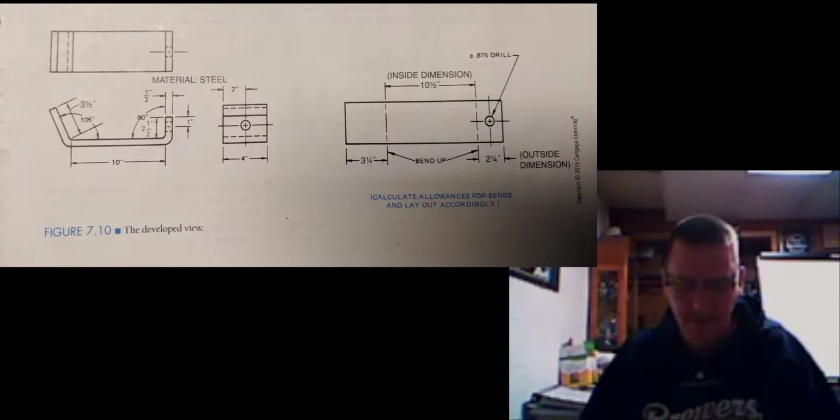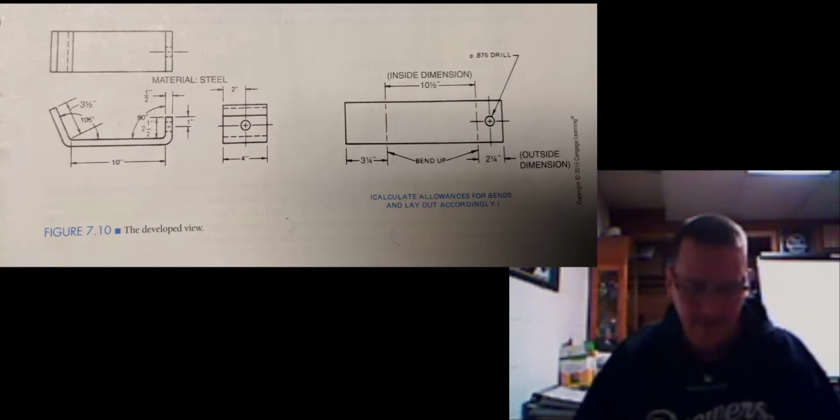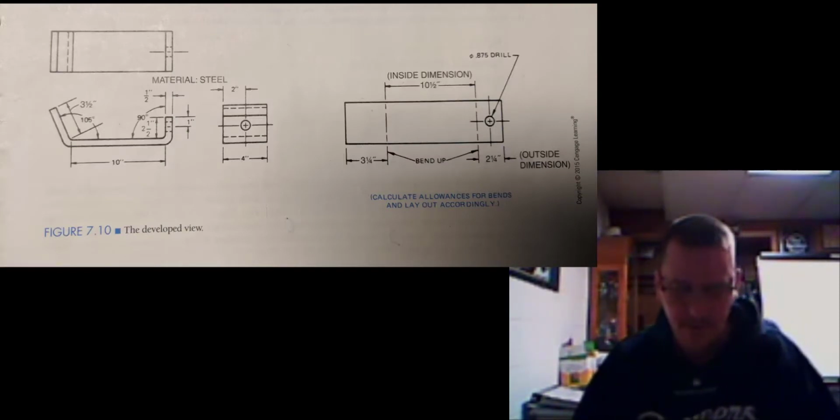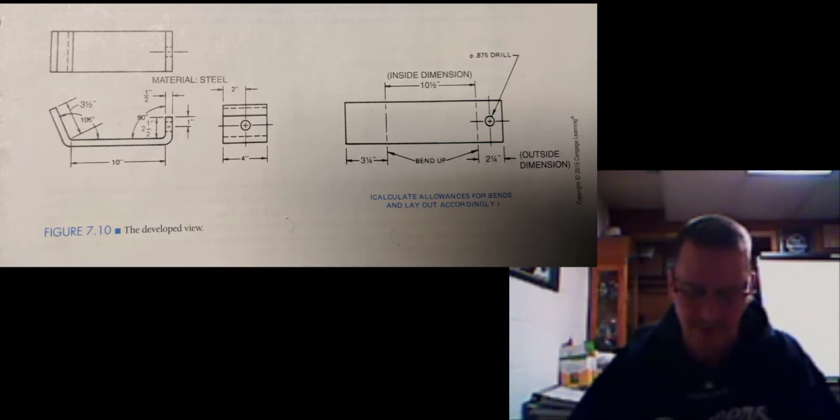Now we come to one of my favorite viewpoints. These are called developed views. A developed view is also called a development. It is a view of a part as it appears when it is stretched or laid out on a flat surface.